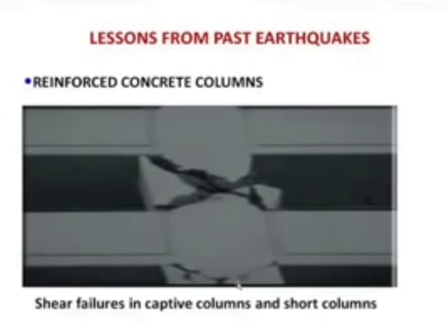No. If they do like that, the stiffness of column will increase by 12EI by L cube, in cubical terms. So you just think, and when they are doing like this, then the column stiffness increases. It will attract more force.